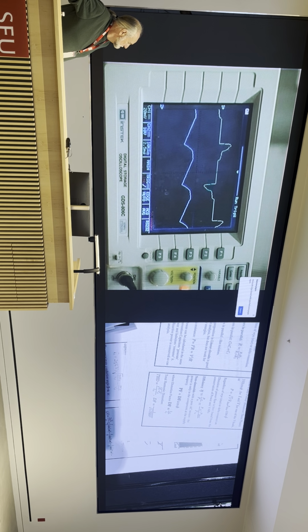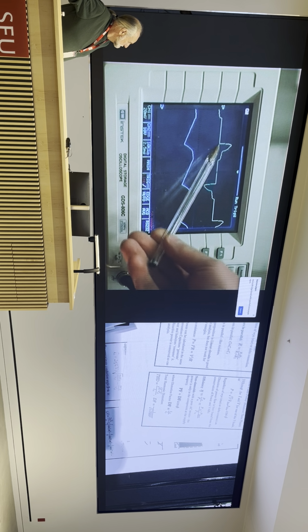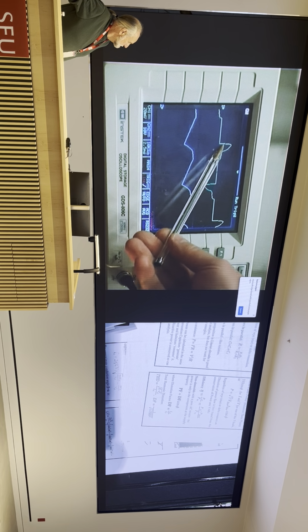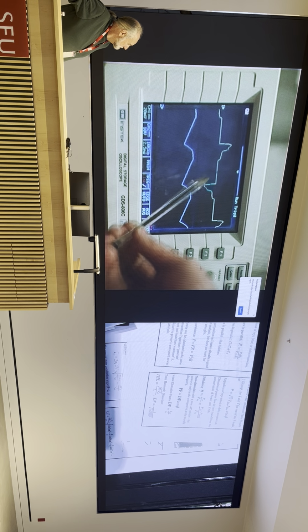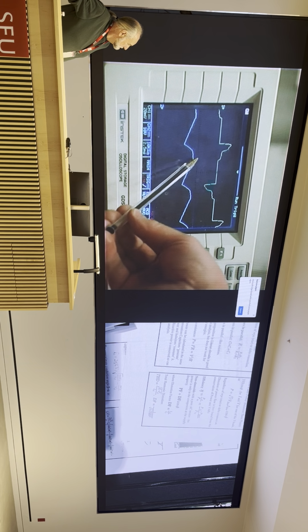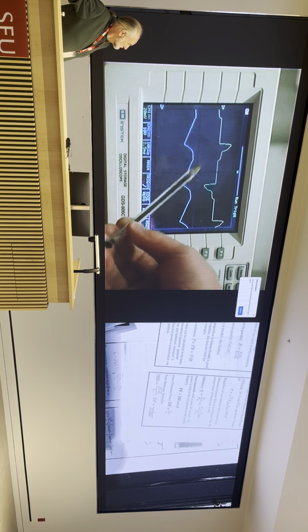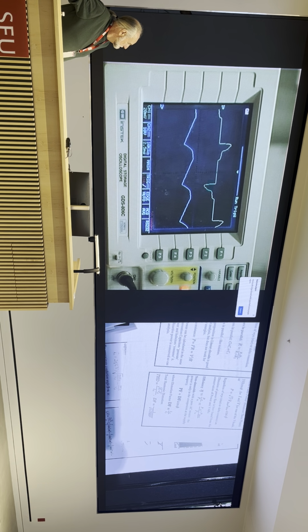So we've got our main rectified voltage with some ripple on it, just as we had in the lecture notes. And you can see during this period here, we're charging. And here's the mains current, a small current charging through there, and then that goes off, and we simply linearly discharge as the capacitor voltage decays.